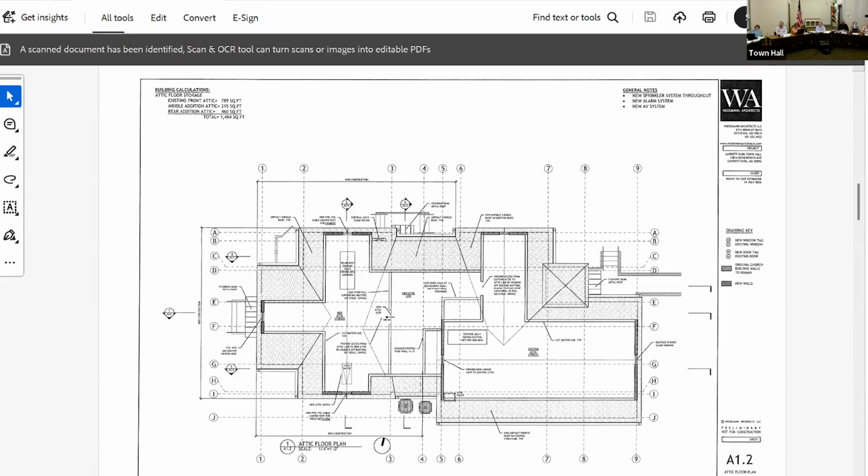There's very little useful life left in this roof. This roof is one of the thinnest asphalt shingles, and I'm pretty sure it's rated for 25 years, technically, but it's diminishing. I believe it's been at least 15 years, so there's somewhere around 5-7 years left in this roof. Since we're trying to match it, we thought this was a good opportunity.